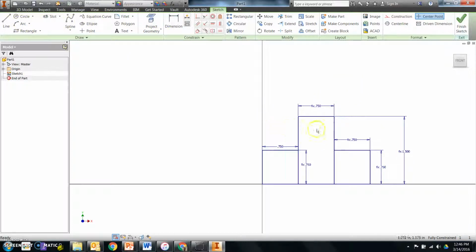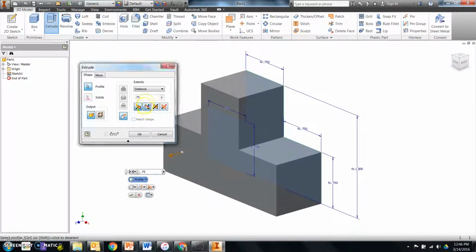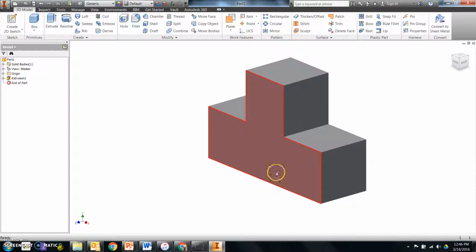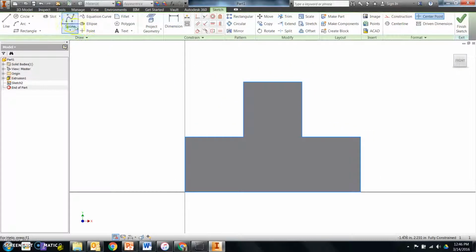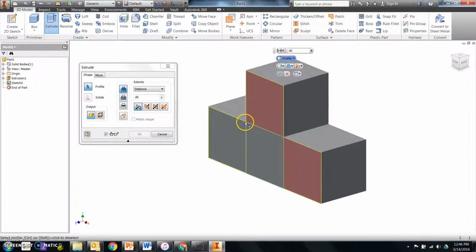Now, that means that this is going to be one big profile, and these will be 2 smaller profiles. If I finish the sketch, I can extrude those, all 3 of them, going backward, and tell that dimension to be D0. And I'll get stuck with this. That would mean that I would either have to create a new sketch, place it on here, and, let's drop in a rectangle this time. Connect this together with a rectangle. Finish my sketch, and extrude it, keeping in mind that that rectangle touched at this corner and this corner down here. Look at what this does. It creates an inconsistency.